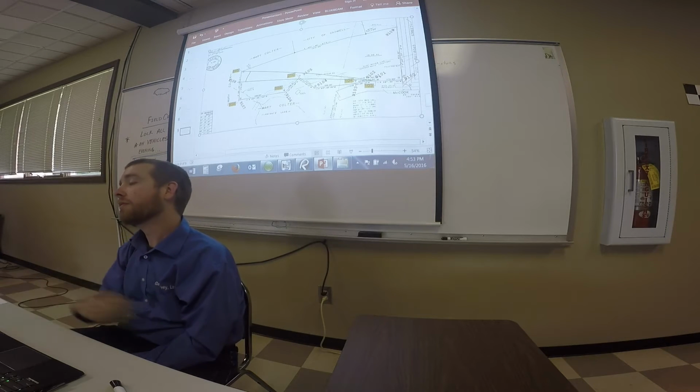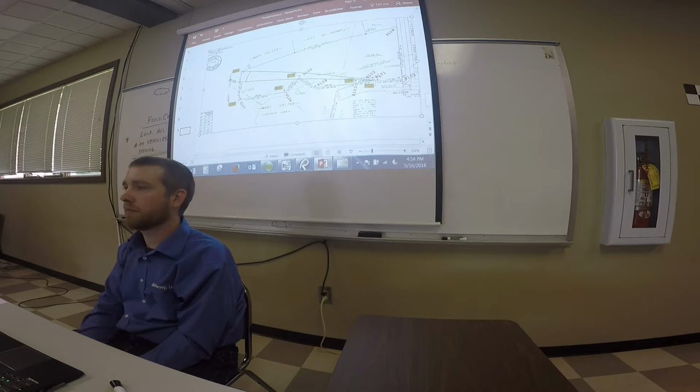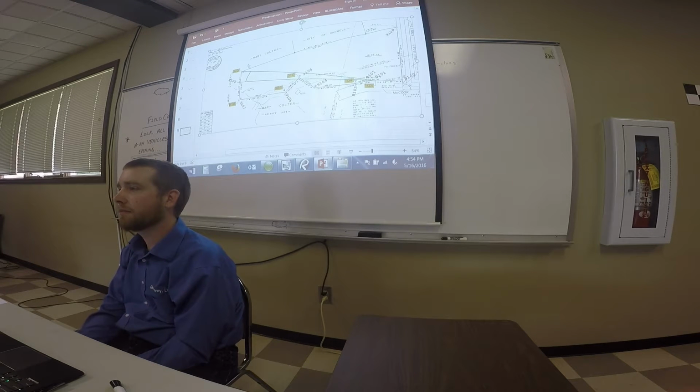Here's a great way of understanding that concept. You can't take a 2x4 and pick it up by the two ends and hold it up because it's too short, right? It's too heavy. Same thing in mathematics. You try to orient that whole site to a little 100-foot distance, it's too heavy out on the ends, and it's going to flop around and be everywhere. But if you grab it by both ends, everything else in between is pretty solid, right? So the longest you can grab.